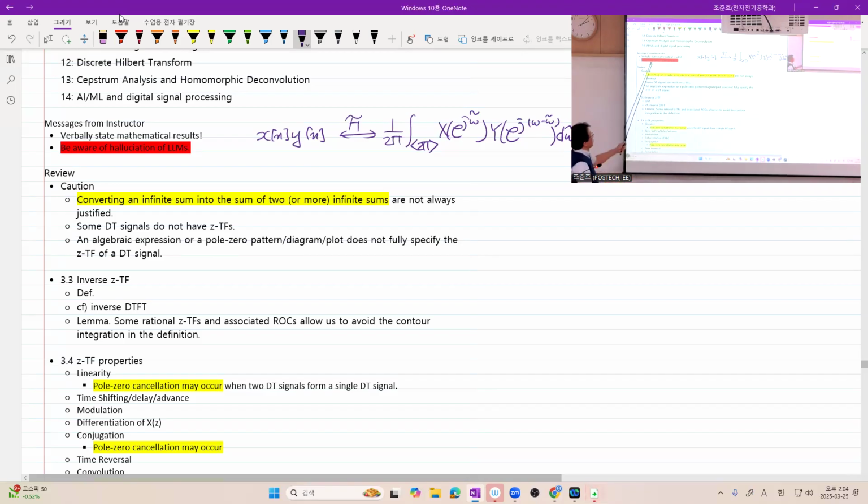And the second one is that sometimes the hallucination of your favorite LLMs gives you completely opposite results, like in the square root raised cosine pulse shaping of digital signals. When the rho factor increases, the bandwidth also increases, so the output signal variation increases because you have larger bandwidth. The problem is that sometimes your LLMs give you the opposite answer, as you've checked from my grading of one of the MATLAB homework problems, right? So be careful when you do your midterm exam and final exam too.